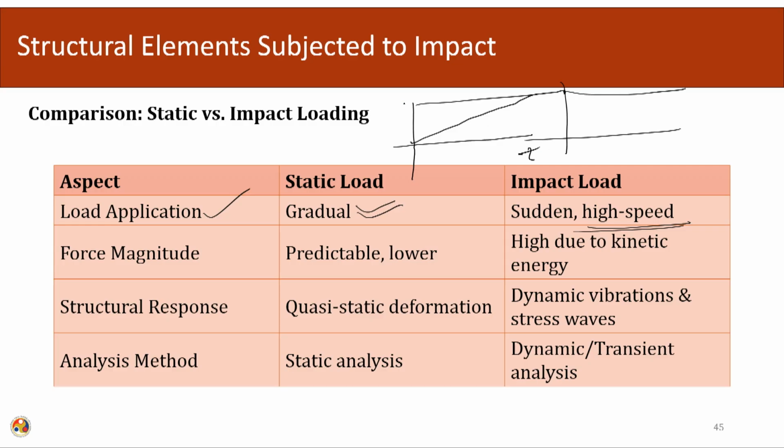So, if this is the magnitude of f, it is applied over a significant amount of time t. But in case of an impact load, f will be applied very rapidly. This will be the f and this will be time t. So, this time t might be in milliseconds, and this time t might be in hours. So, the application of the load, here it is gradual, here it is applied in a sudden sense.